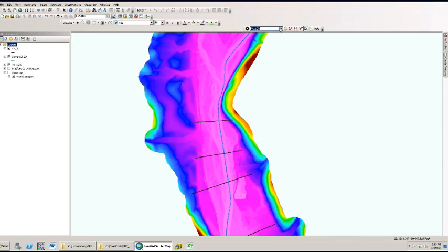Slope values are calculated and returned in a dialog. If there is a surface in the current map document, the Calculate Slope tool will be active to use. Additionally, in order for this tool to work, the map data frame and surface layer must have a coordinate system defined with vertical and horizontal units in US feet.